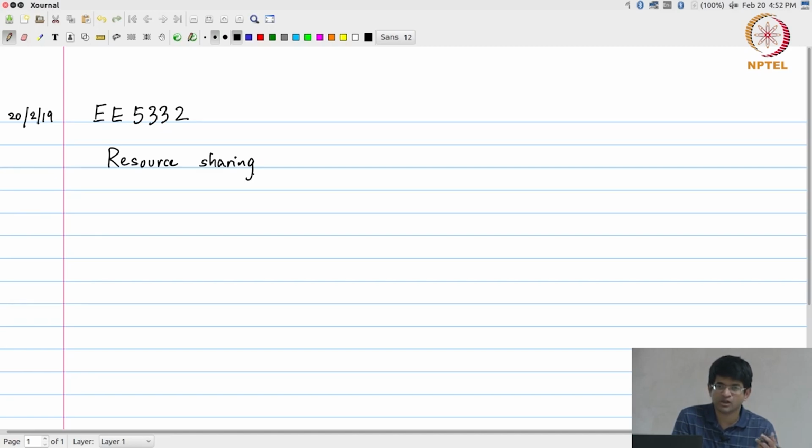Okay, so this is sort of the exact opposite of what we were doing to improve throughput in the case of the parallelism and pipelining transformations, right? Just to recap quickly how we got here: first we looked at representations of signal processing systems as data flow graphs. From there we said the ideal best case throughput that we can get, assuming infinite amounts of hardware availability, is determined by the iteration period bound.